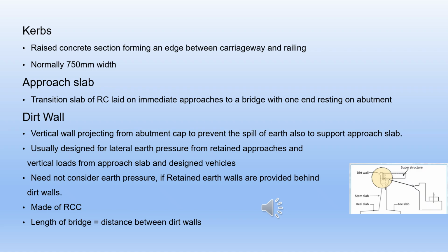Noise barriers are provided at selected sensitive locations, for example near hospitals, academic institutions, etc., to mitigate the impact of excessive noise generated by road traffic. Sound-absorptive or reflecting panels are placed between the source of noise, that is, moving traffic, and sound-sensitive receivers to reduce overall noise levels.